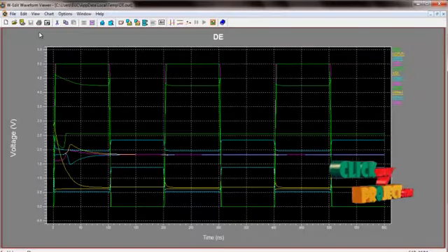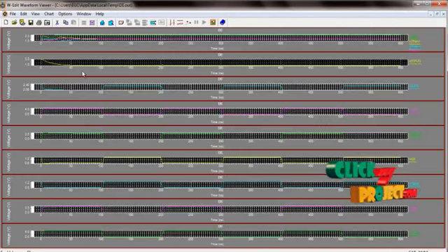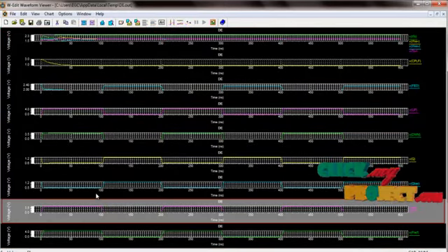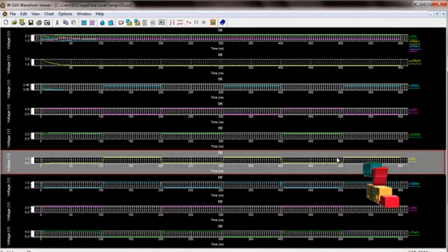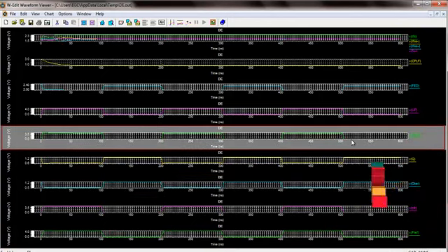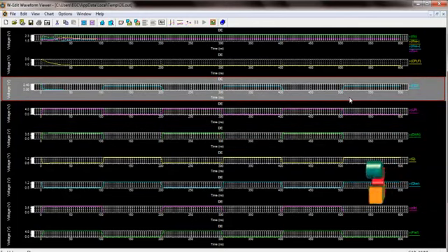This is a push pull voltage controlled oscillator output waveform. Expand this waveform. They are all the output of our product. V clock is an input clock signal. V reference is an input reference signal. VQ is an output signal. VQ bar is an inverse of output signal. This is a down operation. This is an up operation. This is a frequency divider function.